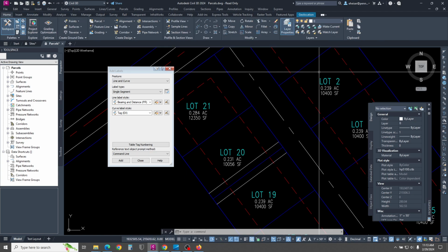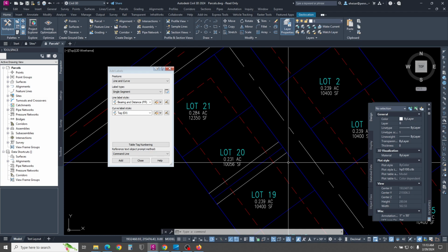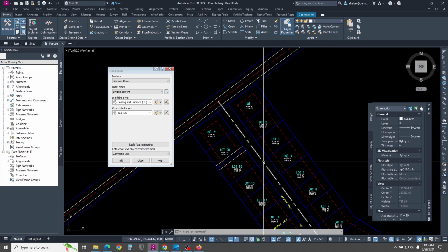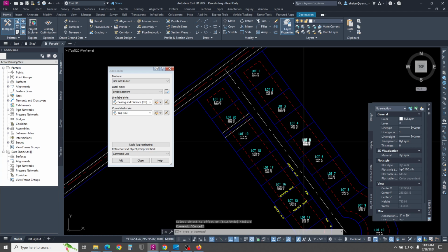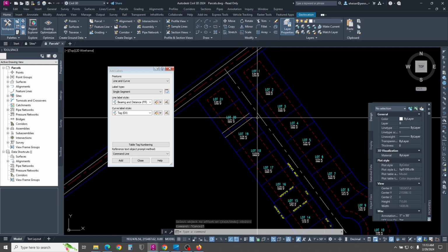So I would do it with your proposed setback lines. Unfortunately, you still have to trim them just like polylines. It'd be nice if there was a way to do it automatically because I know no one likes offsetting and trimming all those lines, but hopefully in the future.